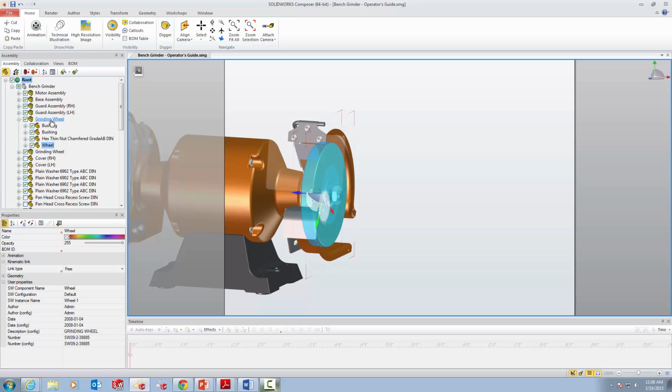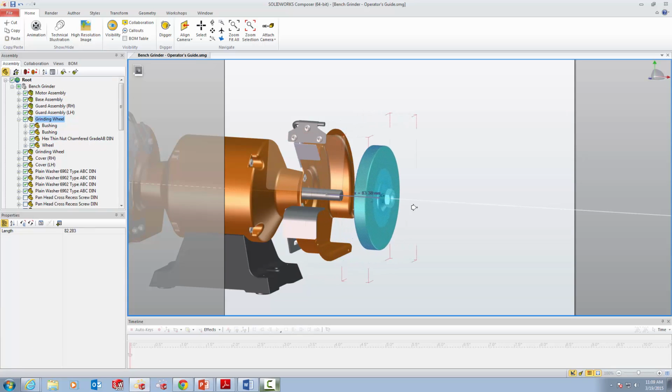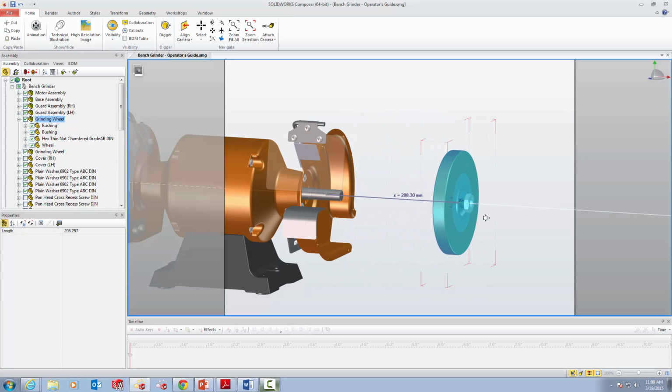So it keeps the subassembly and assembly relationship that already existed right within SolidWorks. So when you select on one part, it automatically highlights where the part is on this parts manager, and you'll be able to see the subassembly that it resides in. So I can just select that subassembly, and now I can move that entire subassembly together.